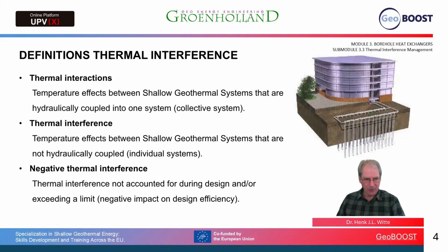Then thermal interference. These are temperature effects between shallow geothermal systems, borehole heat exchangers, that are not hydraulically coupled. So these are individual systems, each with their own design, their own depth, their own number of heat exchangers, and also their own energy profile. They can be different between all the systems.